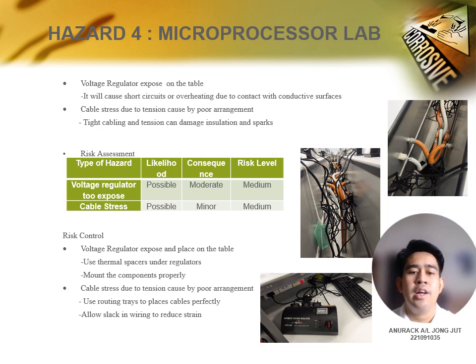First is for the voltage regulator exposed on the table. Use thermal spacers under the regulators so they won't contact the surface directly. Then next, mount the component properly so it won't cause overheating and won't cause a short circuit.